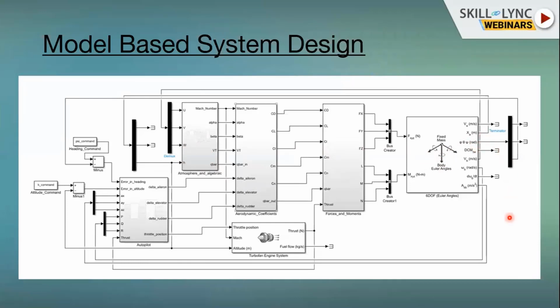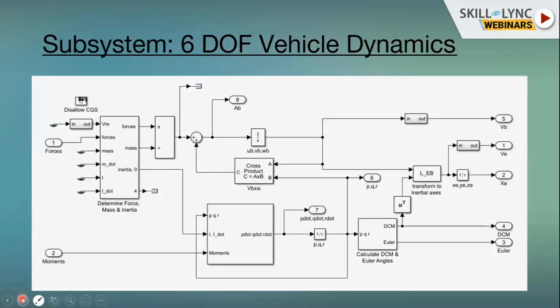And those accelerations and body rates are fed back to the controller to design the control law. So like I said, this is the unmasked version of the 6 degrees of freedom. Whatever you have seen in the equations, nonlinear differential equations, they're captured using Simulink blocks.